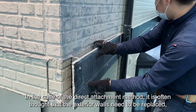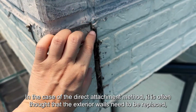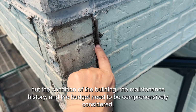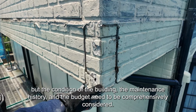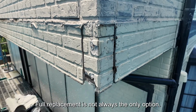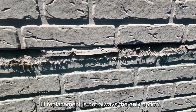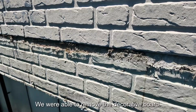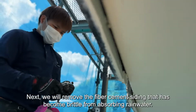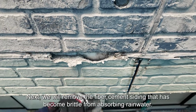In the case of the direct attachment method, it is often thought that the exterior walls need to be replaced, but the condition of the building, the maintenance history, and the budget need to be comprehensively considered. Full replacement is not always the only option. We were able to remove the decorative board. Next, we will remove the fiber cement siding that has become brittle from absorbing rainwater.